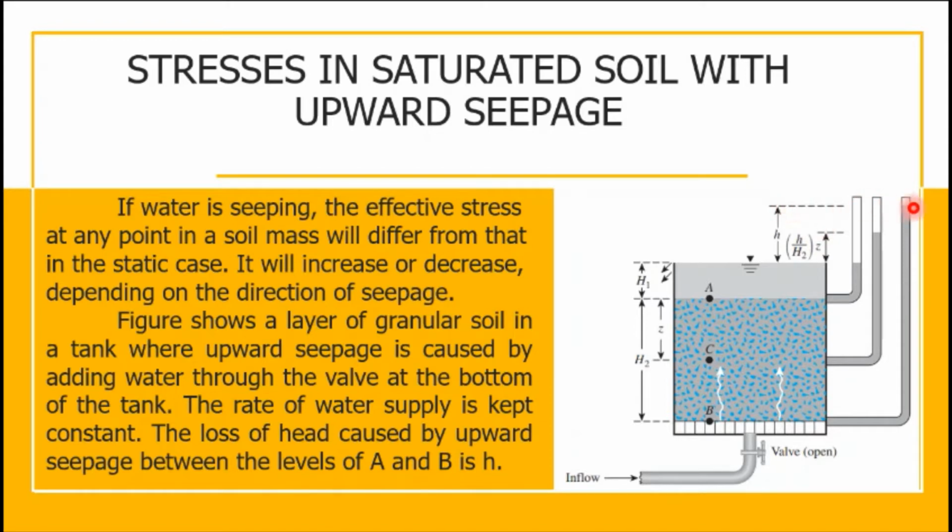And the difference between this level and this level will be the head loss at point B. If we get another piezometer and we put it here, there's another water level here, and the difference between the water level here and the water table here will be another head loss, and that is the head loss at point C. At point A, there is no head loss because this will just be of the same level with the water